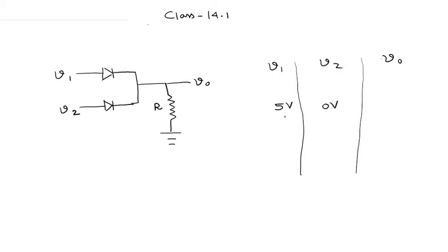Okay, so immediately from our previous experience, we know that if V1 is 5 volts, here this is 5 volts and this is 0 volts over here, then we immediately know, because this voltage is 0 volts and this voltage is also tied to the ground, we immediately know that this diode, let us call it D1 and D2. So we immediately know that D1 should actually be forward biased. Okay, because V1 basically is 5 volts, V2 is 0 volts, and this point is grounded, so D1 must be forward biased. And we also know from our previous experience on problems like this that D2 is actually reverse